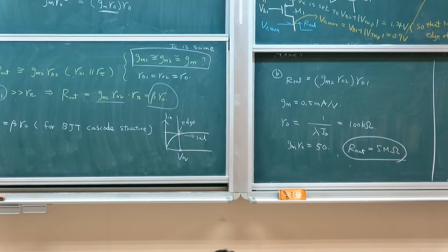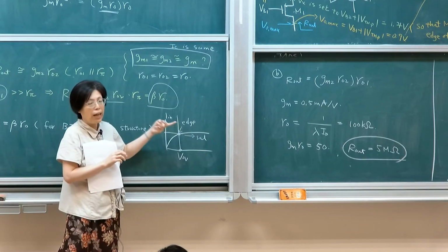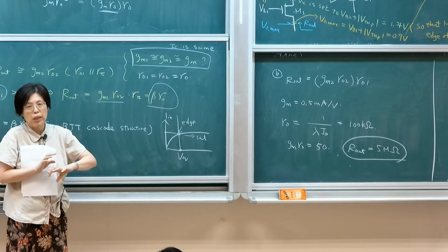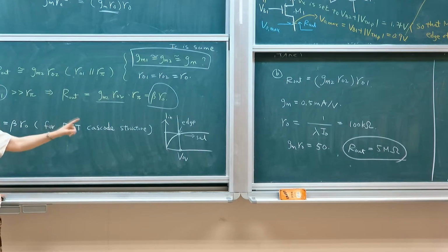So you see that this is a very powerful tool to get large resistance. Because I've said it many times, it's actually very hard to construct resistance, especially large resistance in an integrated circuit. So you typically want to use transistor characteristics to effectively give you current-source-like or high-resistance-like behavior. By stacking two transistors, you use much less area.